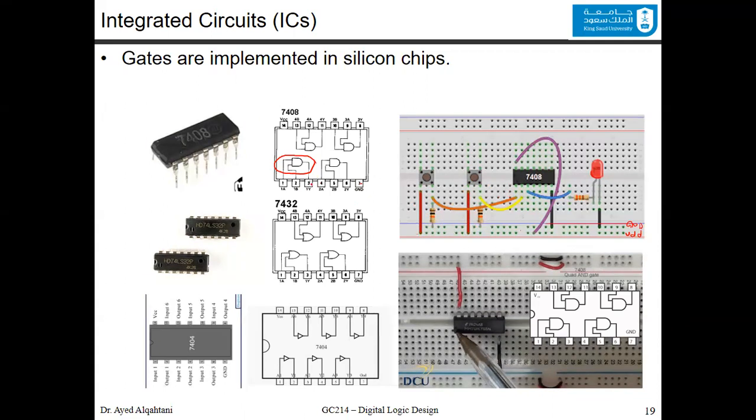And to test the AND gate, you get the result in pin 3, and then you connect it to this LED. You can see in the LED, you have 2 pins. One of the pins we connected to the ground, and the other pin we connected to this output. I should mention that all this column is connected together here. So this one you connect here, and after that you have this connection to the LED, and this goes to the ground.